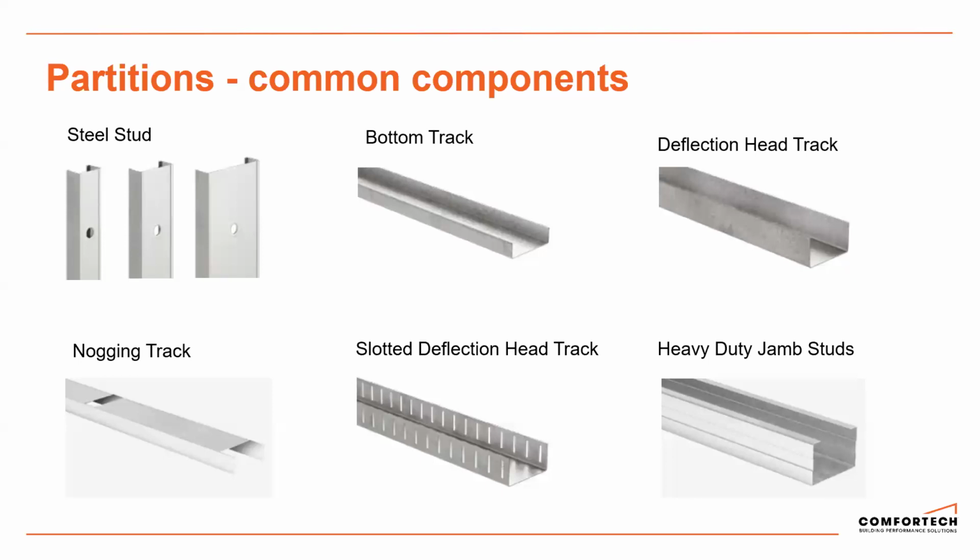Noggin tracks are used to keep the studs in line and stop them from twisting. All manufacturers will have a table showing noggin requirements in their design guides. Again, the different types of deflection head track shown will allow for a range of wall types and head connections.